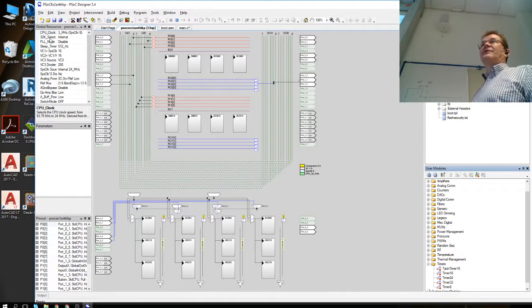So it's about power 14. So that's the divider for our clock divider. We start from this one and divide it by 2 to the power of 14, which means a 16-bit counter. And this one would be giving the interrupts. Good. So we need a 16-bit timer.